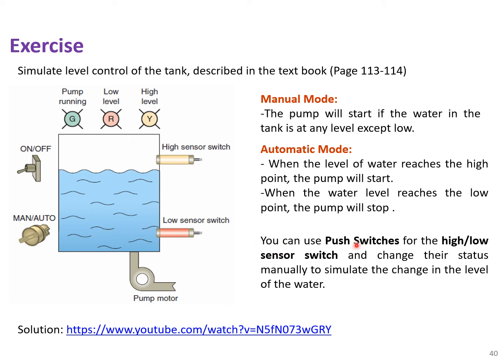Okay, you can use push switches for the high and low sensor switch. In the visualization in CODESYS, you can use push switches for the high-low sensor switch and change their status manually to simulate the change in the level of the water.